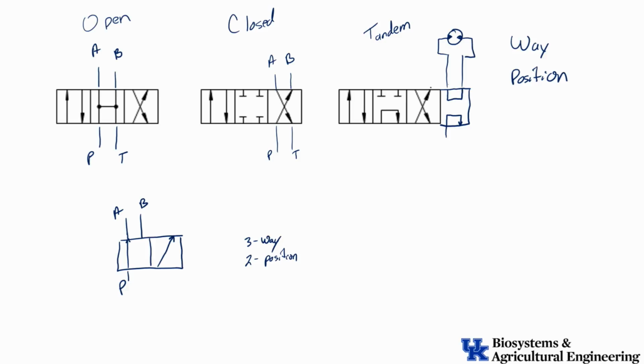And if we were running this machine in either the retract here, the cross position, or the straight through position, so either turning the motor clockwise or counterclockwise, and we stopped it suddenly and went to the center position, if there's a lot of inertia, the mechanical load on that motor is still spinning, it's going to want to try to keep spinning that motor. And this is like in electronic circuits, where we talk about inductive kick. If we have a big inductor in there and we shut off the circuit, we get a big high voltage spike and it makes a spark in a switch or something like that. And the same thing can happen here.